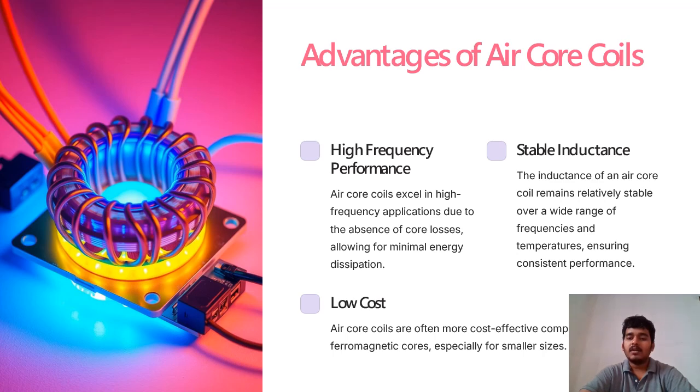The inductance of an air core coil remains relatively stable over a wide range of frequencies and temperatures, ensuring consistent performance. It is low cost. Air core coils are often a more cost effective component than ferromagnetic cores, especially in smaller sizes. It is low cost because the air core coil doesn't have any core. It is already known that it is an air core coil. Air core means it doesn't have any core, so it is very low cost.